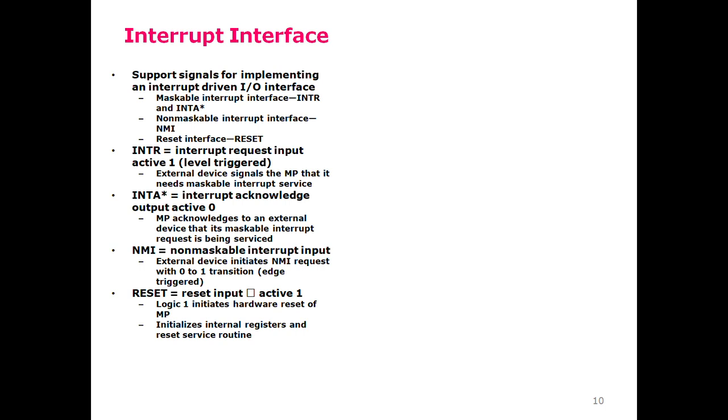And then after the input and output device is ready to perform that operation, it signals the microprocessor that the assigned task has been completed. In this technique, the microprocessor is always busy executing instructions and is not waiting for the slow devices. So it enhances the performance of the microprocessor.